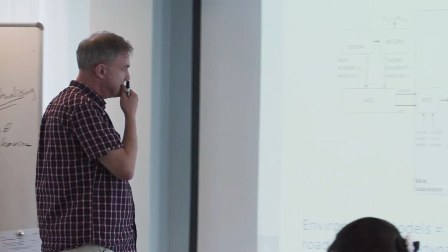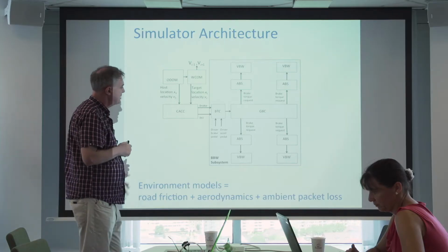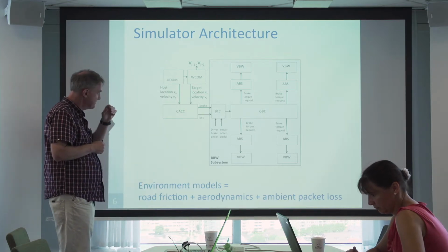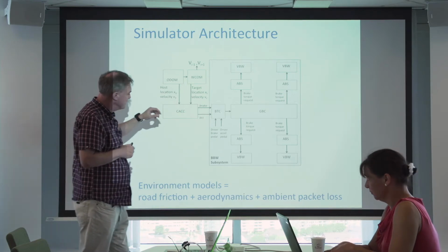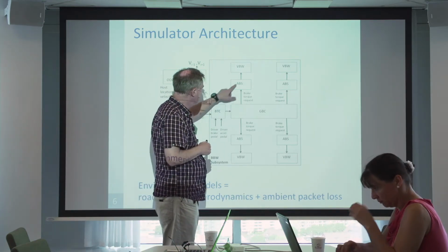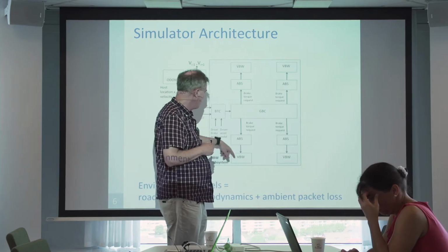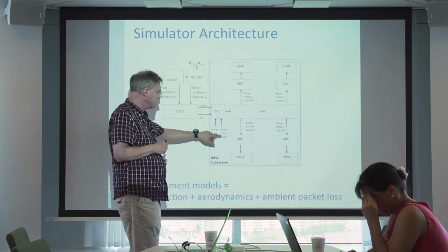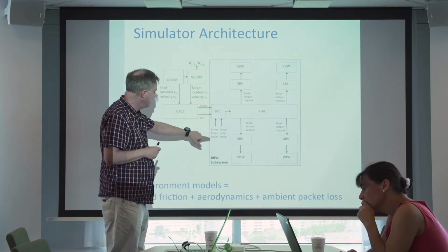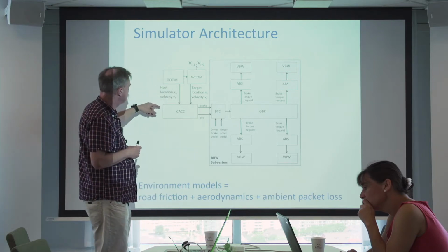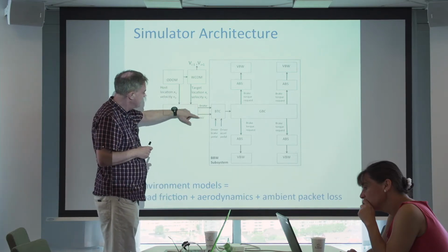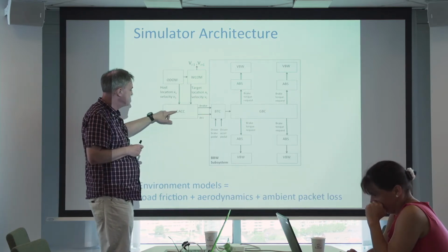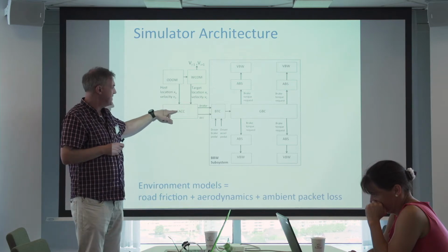So the simulator is quite streamlined. Nowadays we're also moving to more complex, physically complex simulators. You'll see some results later on. So basically there's a brake-by-wire system here. These are ABS units on the wheels. This is a four-wheel vehicle model. And there's a global brake controller that takes the manual signals only from the lead driver. So these are switched out for the following vehicles, which instead generate their brake and gas values by applying an ACC algorithm. Here we just use PID algorithms.